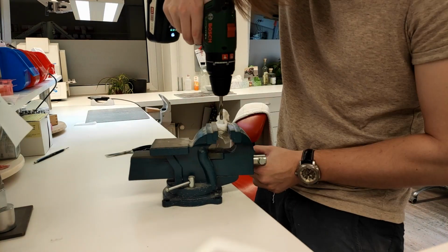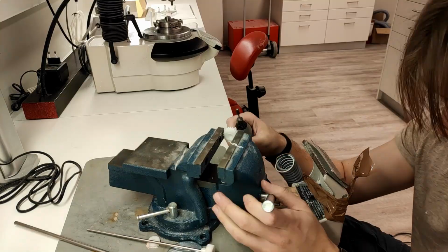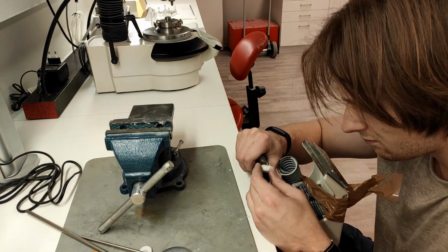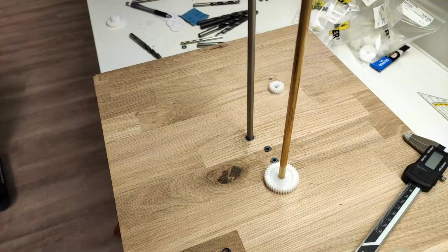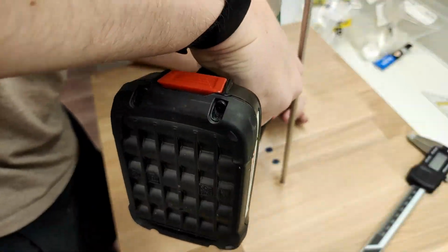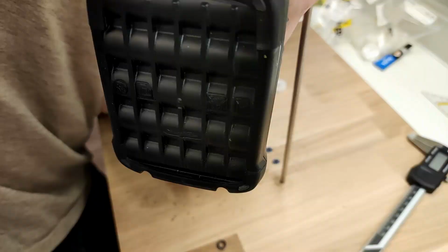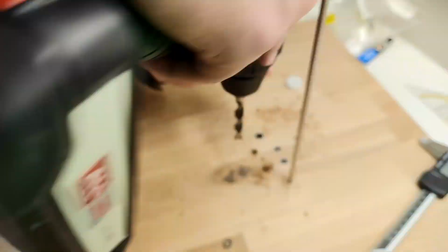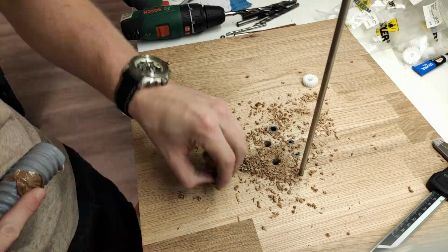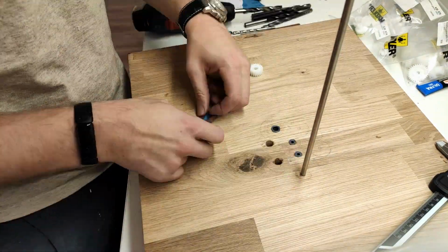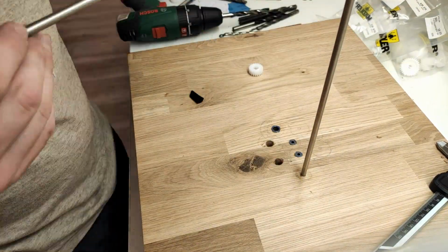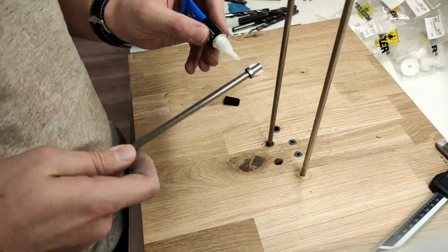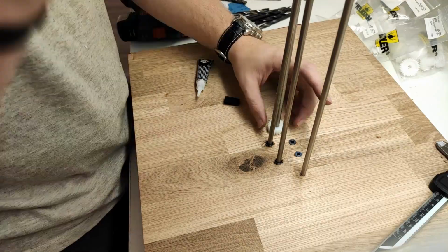Here you can see me widening the hole of one of the gears using just a regular battery drill, and this is also the part where a drill press would be most useful. Since you have to operate the drill with your hands, you can't get a perfect perpendicular hole into this gear. And this means if you have a chain of multiple gears which all have not a perfect perpendicular hole, the gears will just not sit at a perfect right angle onto their axis, and this will not only cause stress to the gears but also will cause some stuttery motion, which you will see in some of the bodies of the final model.